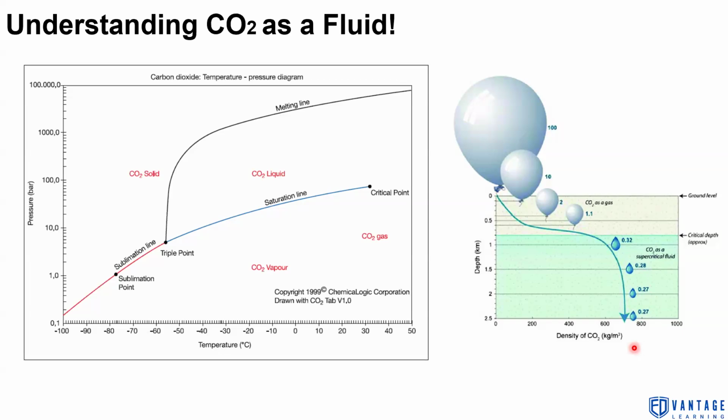So the main objective of compressing CO2 to a temperature of 31 degrees centigrade and a pressure of approx 7,400 kilopascal, which is approx 90 to 100 bars, is to have that phase transition, neither liquid nor gas, but to a supercritical state.